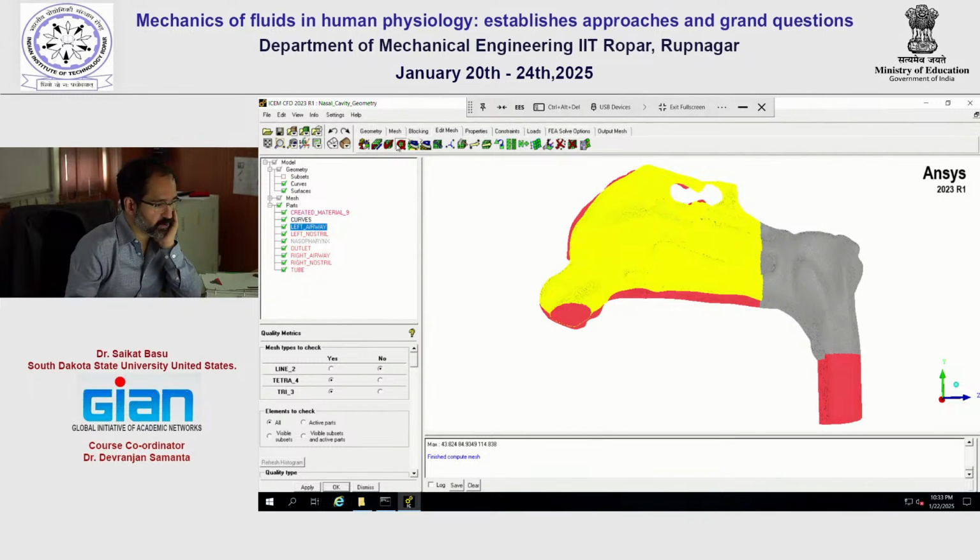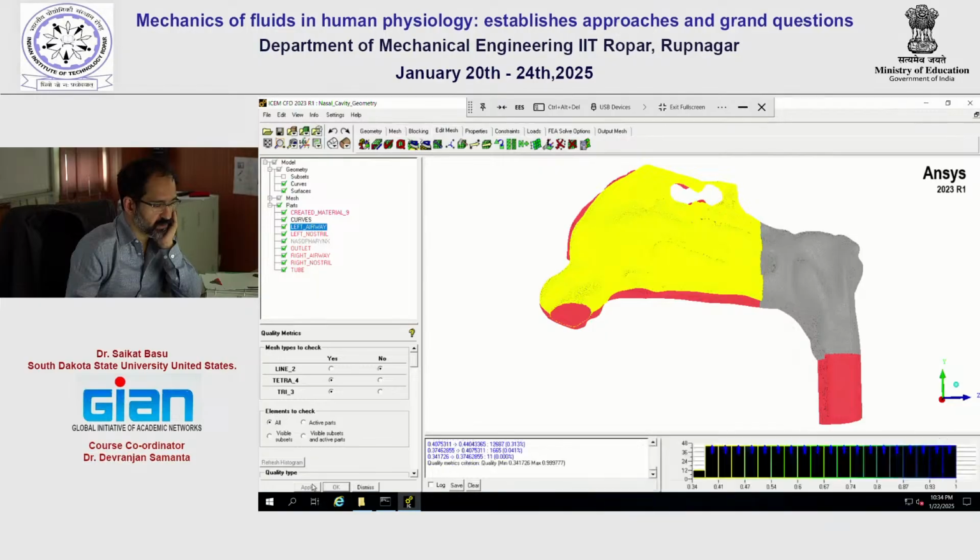Okay, so if I go to this fourth tab under Edit Mesh, Display Mesh Quality, and press Apply, you'll see that they classify the meshed elements in terms of their quality. How do I define quality? It is how smooth the geometry transitions are from one mesh to another. The thing that we track is in the worst quality bin, which is the bottommost menu, if the percentage is close to 0%, which it is. But if it is not, there is a way to smooth the mesh as well.